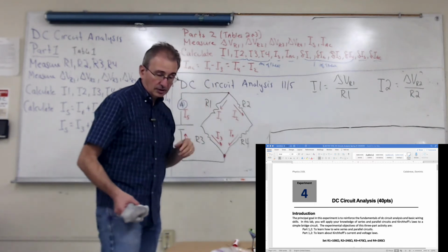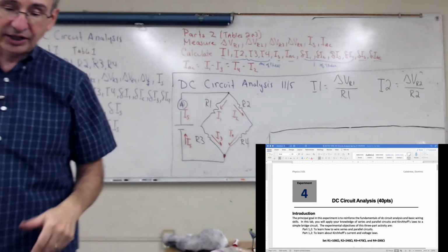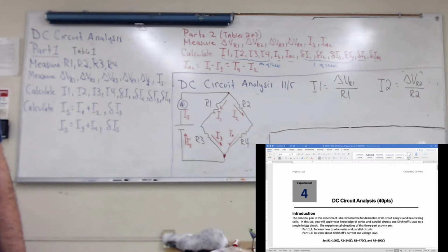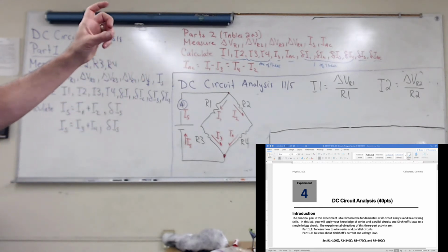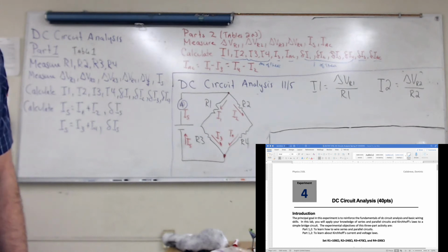Which scale reads in kilo ohms? All the ones that have a letter K in them, that's kilo ohms. The ones that have an M in it are megohms. So on the 2 megohm scale, the values will be 0 to 2 megohms, and the unit will be in megohms. So a 1,000 ohm resistor on the 2 megohm scale will read 0.001. Okay, that makes sense.